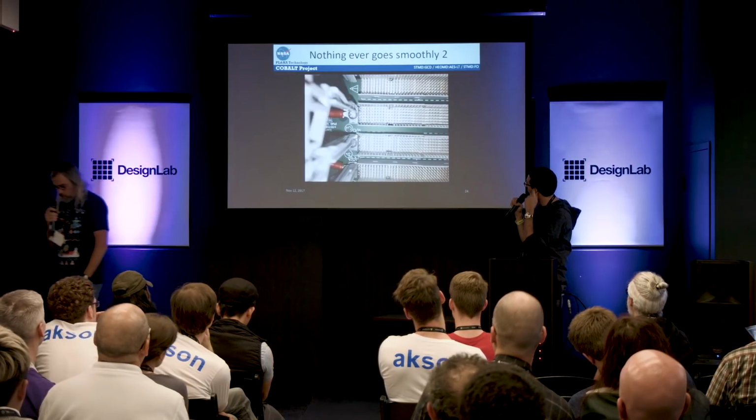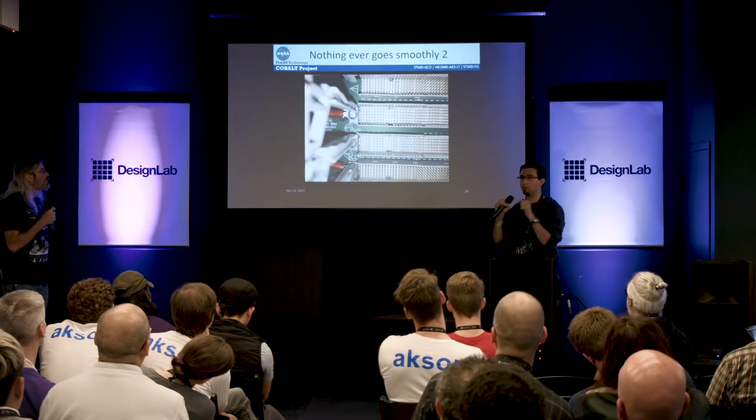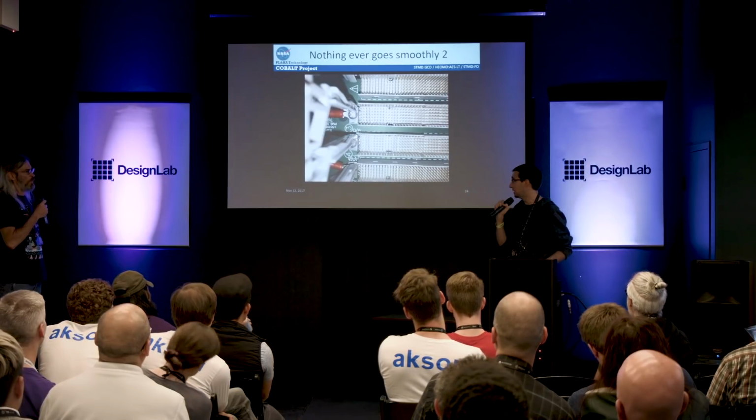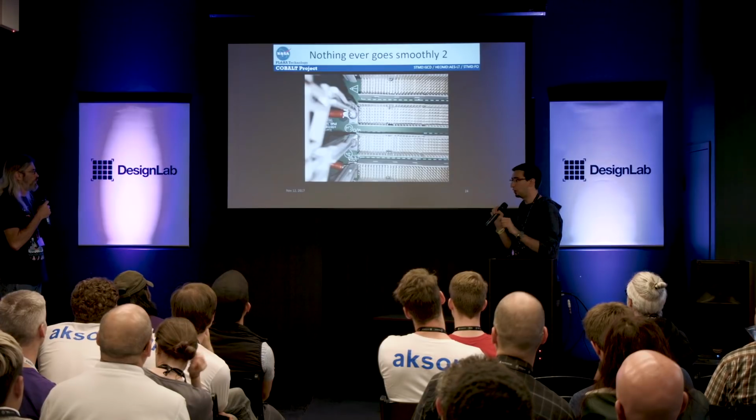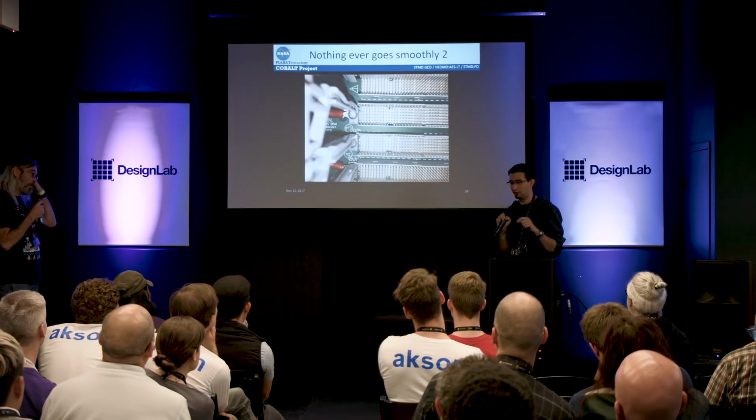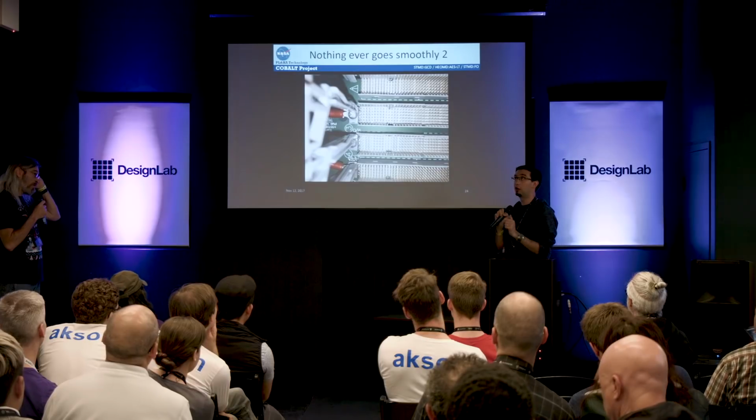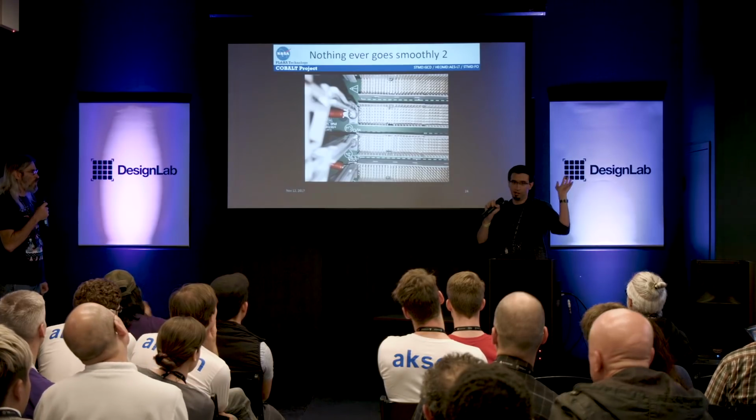And so earlier I mentioned it's a blind mate, right? You put the card in, you don't know how well it's seated. We seated the card the first time, and suddenly our overcurrent protection kicked in and went, oh no, I'm not turning things on.